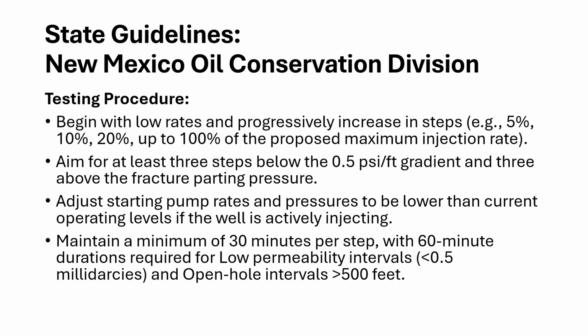They also let you adjust starting pump rates and pressures to be lower than the current operator limits if the well is actively injecting. If you have an average injection rate, start below that. And they recommend a 30-minute minimum, with 60-minute durations for low permeability formations.